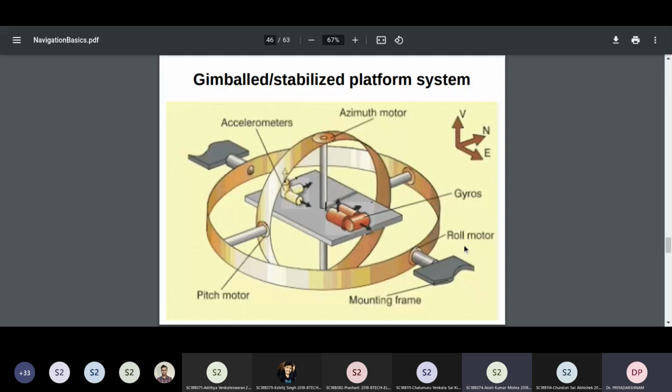Sir, because of friction there is some additional rotation rate, and because of normal rotation of the engine there is some rotation. So how do you know which rotation corresponds to what? No, the inner gyroscopes will measure only the frictional quantity. Otherwise, the platform is stable, no? If the bearings are frictionless, the platform is stable. The rotation is only due to friction.